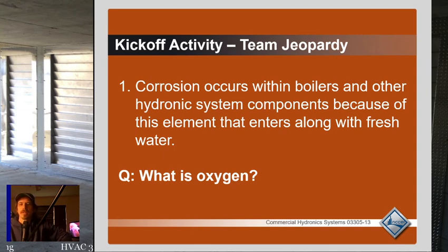How can I make sure that this is as serviceable as possible? And how can I make sure that even when repairs need to be made, as little oxygen as possible is going to be reintroduced to this system. On chill water especially, anytime you have to make a repair and put insulation back, make sure you do the insulation very well with a very good vapor barrier, or you're just going to cause more problems down the road. I have a very love-hate relationship with hydronic systems because of that.